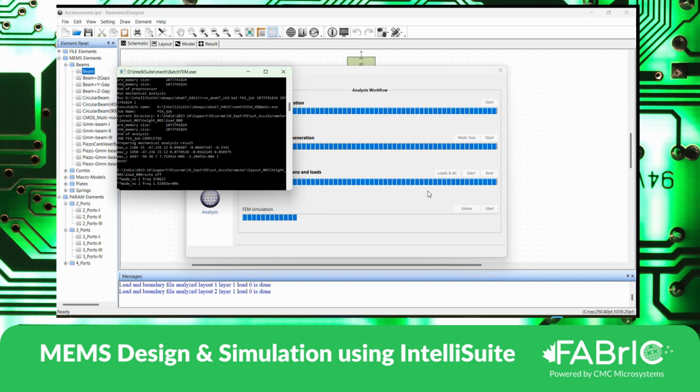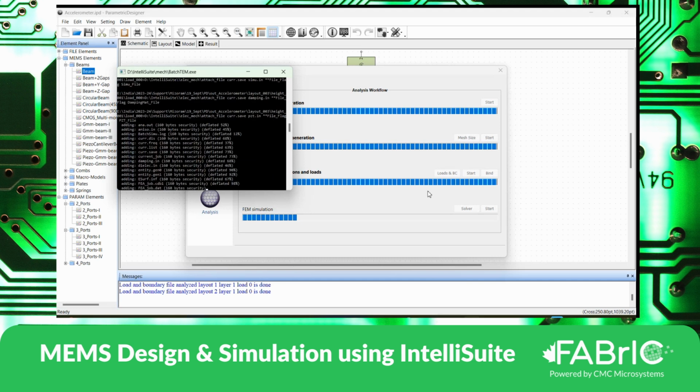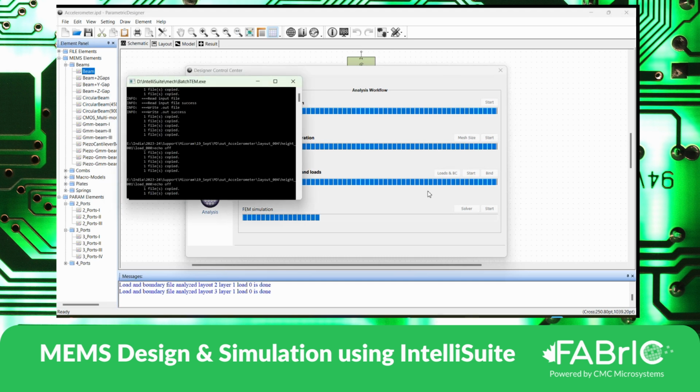If it is thickness parametric simulation, it's straightforward, UI based. If it's an X and Y geometry, that is horizontal or planar geometry parametric, then a small VB script needs to be written.